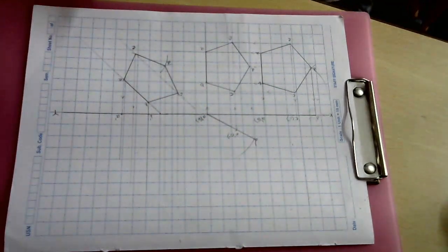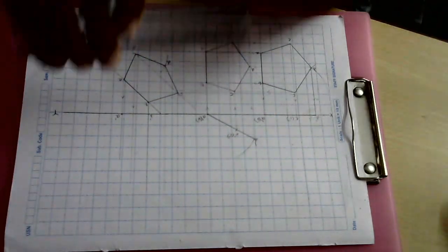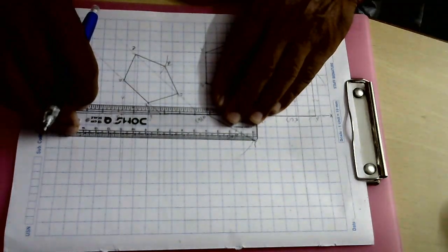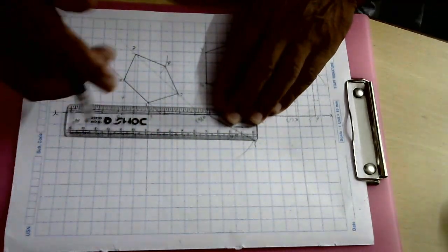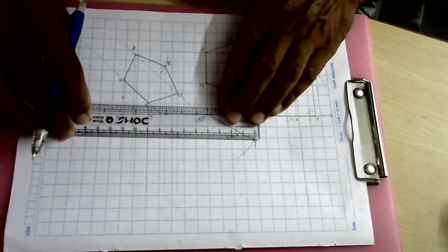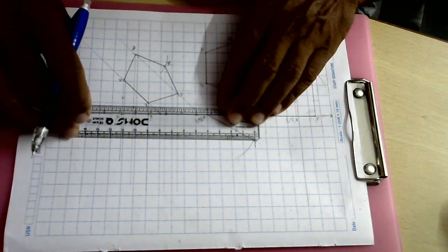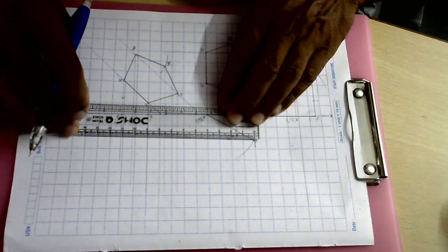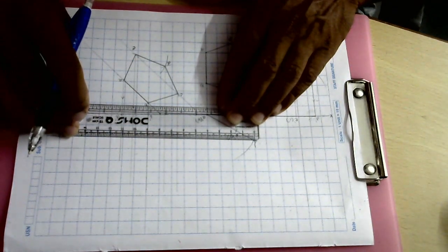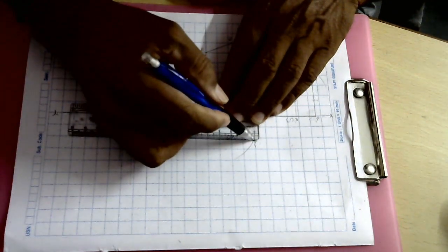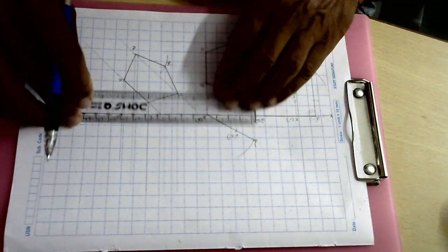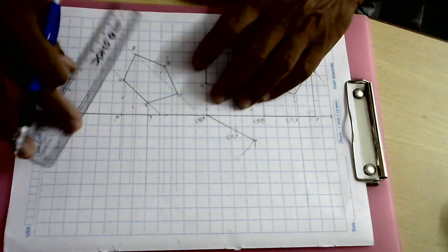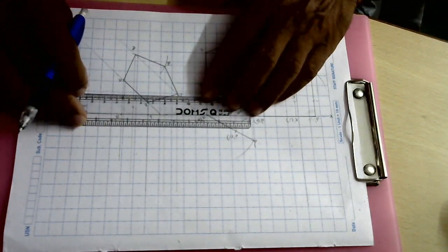Okay. Now to get the other points in the front view, from the rotated position of the plane, you just draw some construction lines again here. Draw these construction lines towards the right side. Now this refers to point D. I gave an idea how to get the construction lines exactly perpendicular.